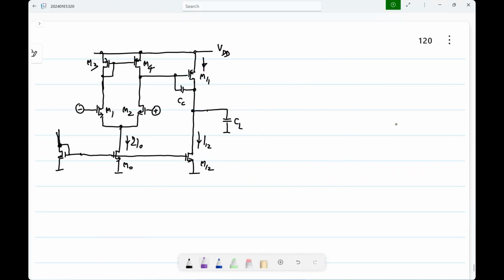Now, there is one more thing that is possible, that is, this is again only in limited context. You can actually use AC coupling. I already said earlier that normally inside an op-amp you prefer not to do it, but if that is permitted, at least for one side of it, you can use AC coupling. That is, you use some large R bias.